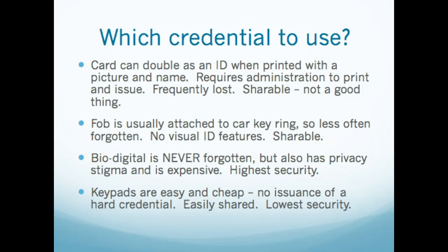So again, read the article for this week as part of the reading. It will give you some insight as to which credential you may want to use for our project and for future projects. For the most part, I would say that probably 95% or more of access systems in the U.S. use an ID card type credential because it doubles as the ID. People are required to carry it. You have some visual cue as to whether the person who's carrying it is that person at all, and they're relatively inexpensive. Depending on the technology you get in it, they run between $3 and $7 each.